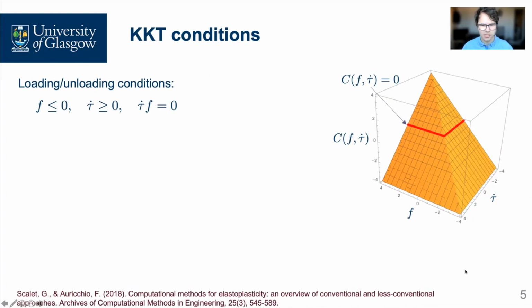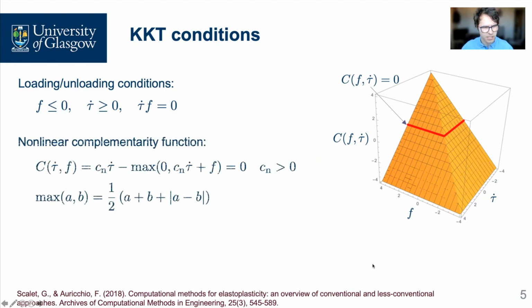Before we can solve the system in a weak sense, we need to get rid of these inequalities of loading and unloading conditions. There are many ways to do it. We decided to use the established so-called complementary function like this. It is very often used, for example, in contact mechanics.